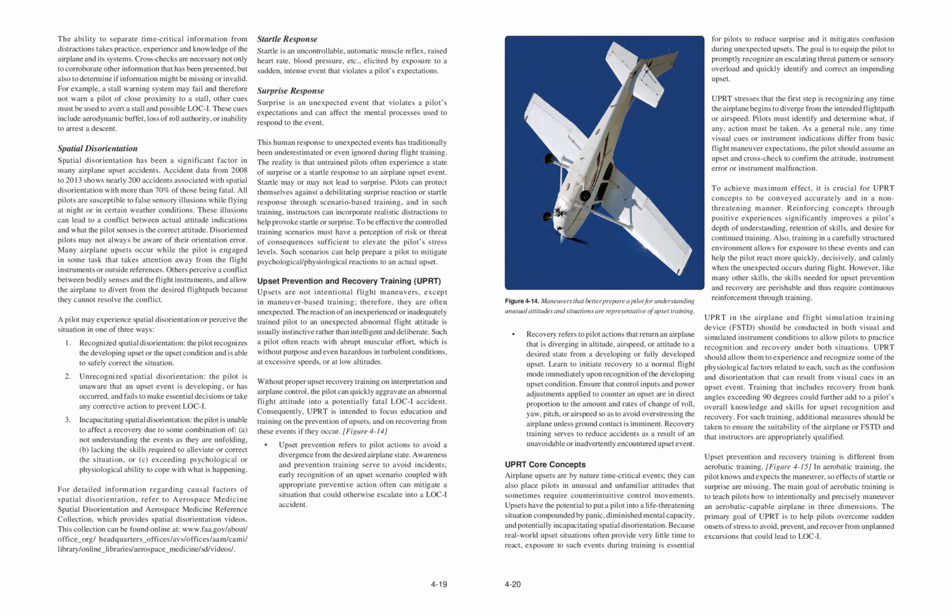To achieve maximum effect, it is crucial for UPRT concepts to be conveyed accurately and in a non-threatening manner. Reinforcing concepts through positive experiences significantly improves a pilot's depth of understanding, retention of skills, and desire for continued training. Also, training in a carefully structured environment allows for exposure to these events and can help the pilot react more quickly, decisively, and calmly when the unexpected occurs during flight. However, like many other skills, the skills needed for upset prevention and recovery are perishable and thus require continuous reinforcement through training. UPRT in the airplane and Flight Simulation Training Device, FSTD, should be conducted in both visual and simulated instrument conditions to allow pilots to practice recognition and recovery under both situations.